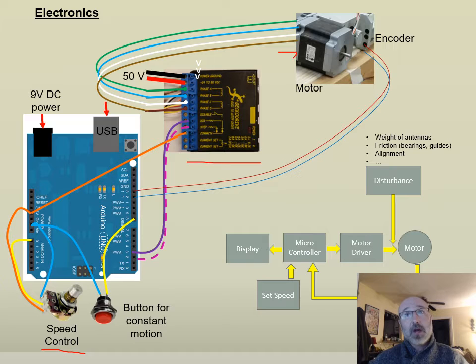On our motor here, I have an encoder that gives feedback along here back to our microcontroller. So this is our feedback loop, and we can see that in the diagram down below, which is the same as the first page, where we don't necessarily need to use this potentiometer anymore if we're using the information provided from the encoder to send back into our Arduino board. So we start up the system. Our motor starts spinning at a set RPM. Our encoder is telling us the speed of that motor, the RPM, sending it back in here.